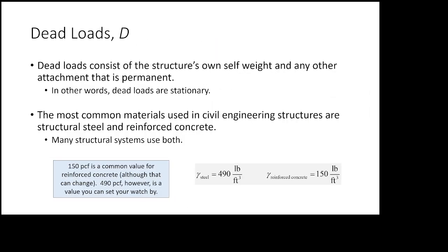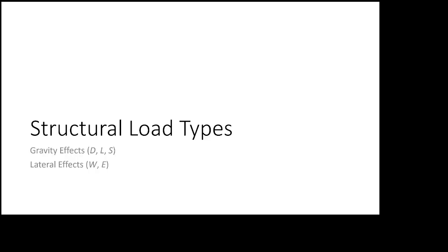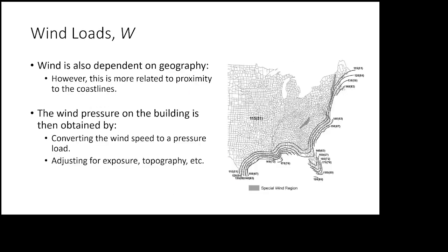In fact, if you look here at your load combos for wind, a lot of the wind ones are 1, because the idea is that these values are sort of already factored. That's kind of the idea. Now, the vast majority of the country has a design wind speed of 115 miles per hour.